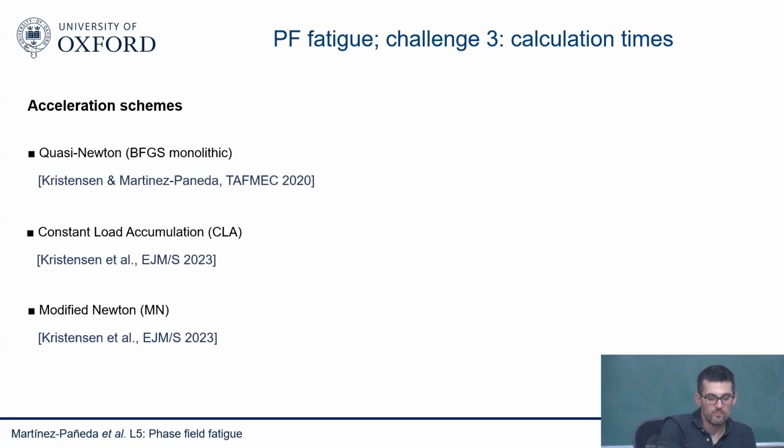So that's a problem. Normally in fatigue, the way engineers get around it is by assuming linear elasticity, superposition, and you basically do Miner's rule, so you accumulate damage here and there, and some sort of accumulation of damage based on superposition. That's okay. I mean, it has worked for many years, and some things are falling down, but not everything is falling down. But there are many situations where this doesn't work out very well. If you have an overload, or for example, when other phenomena happen like corrosion fatigue and so forth. So being able to actually handle any arbitrary loading history, that's very powerful.